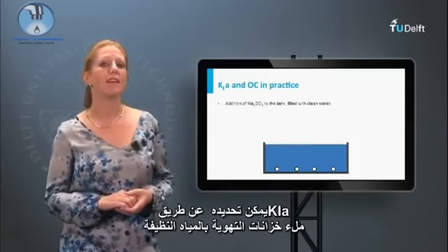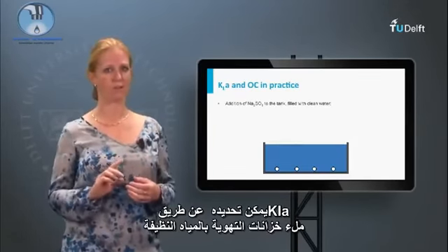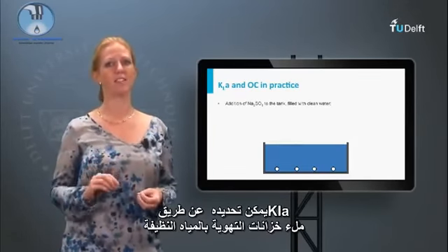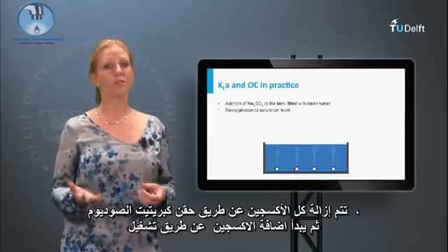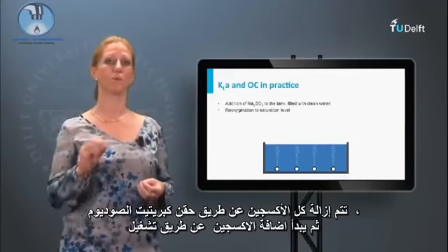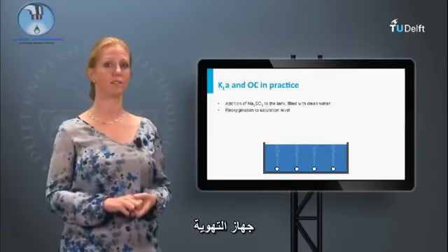The KLA for an installation can be found by filling the aeration tanks with clean water. All the oxygen is removed by dosing sodium sulfite, whereafter reoxygenation starts by switching on the aeration device.